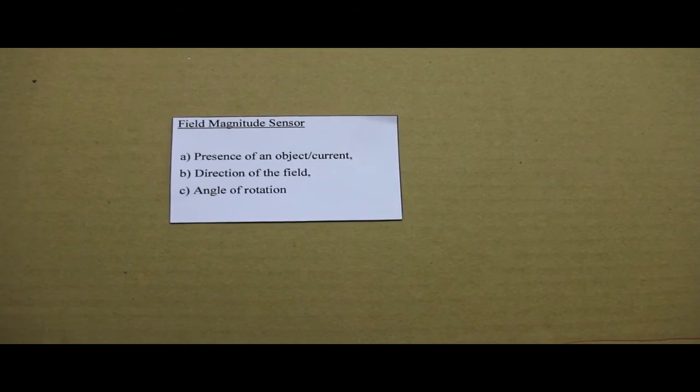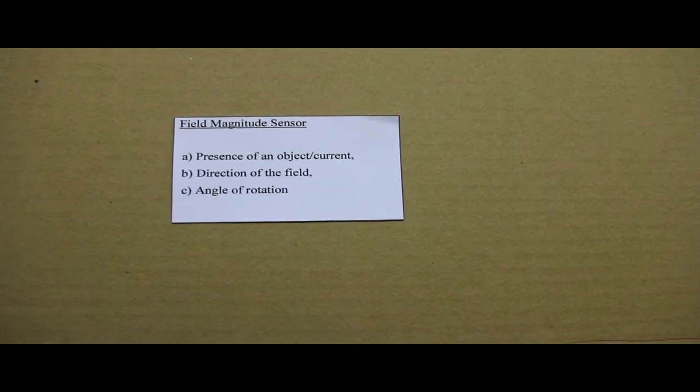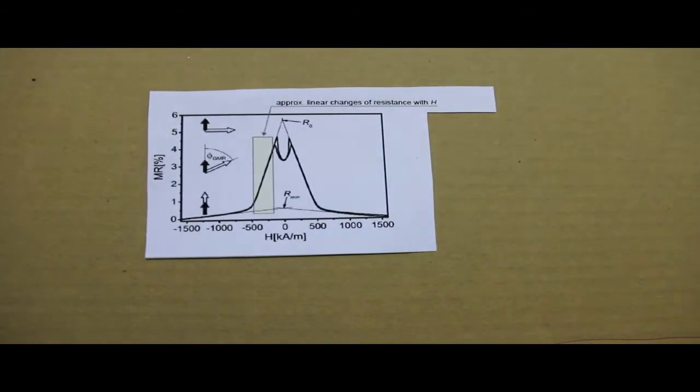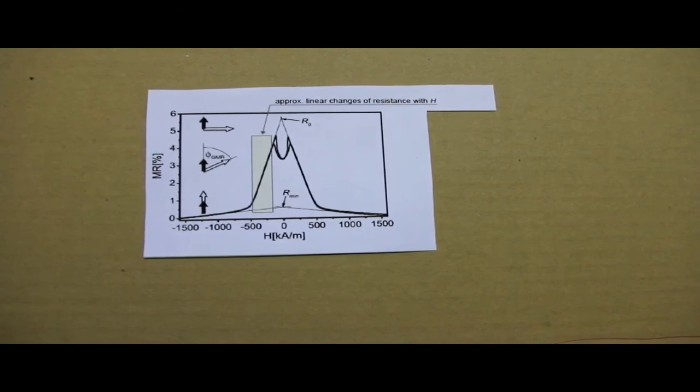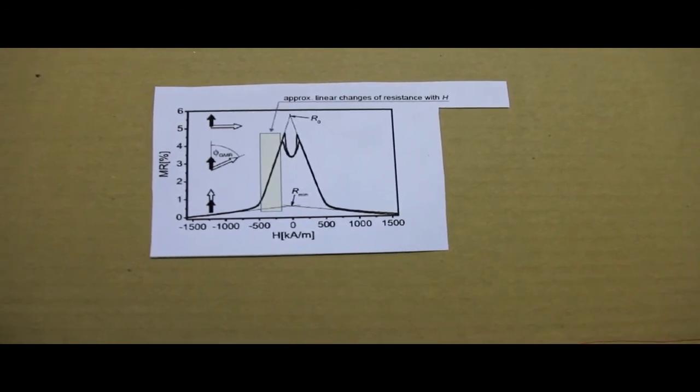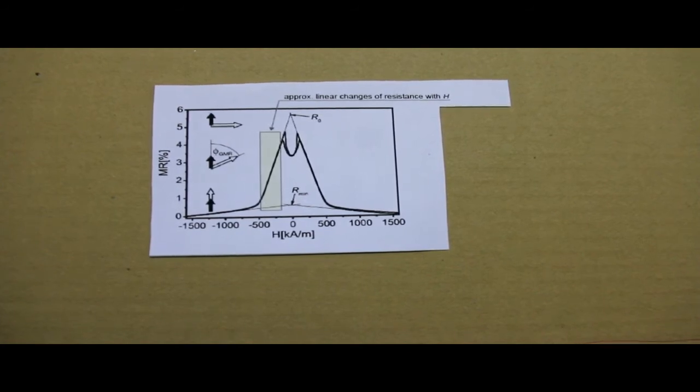From the graph we can see that the resistance change in the linear range of the R versus H dependence is related to the reversal of the iron-nickel layer. The saturation field is determined by the shape anisotropy of iron-nickel layers. The hysteretic range is not useful for applications, because both cobalt and iron-nickel layers' magnetization directions change.